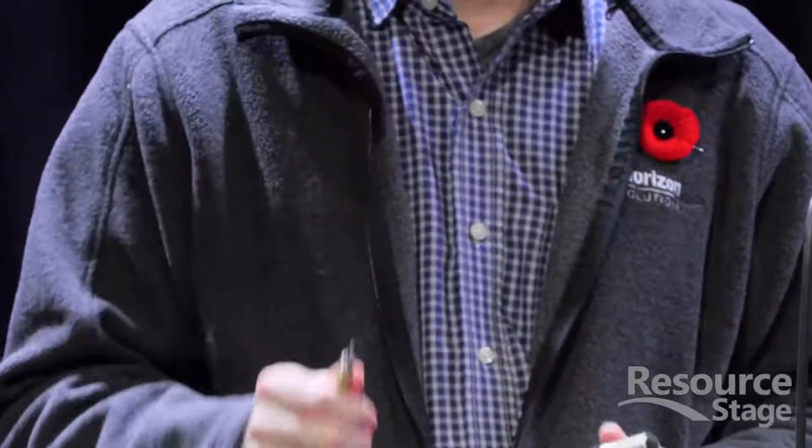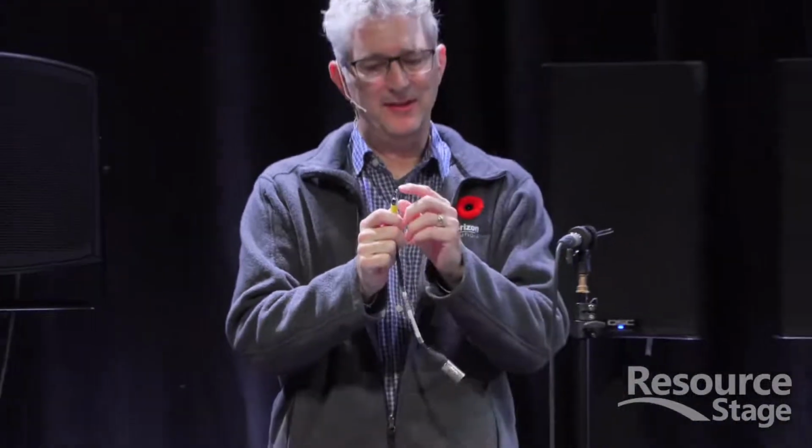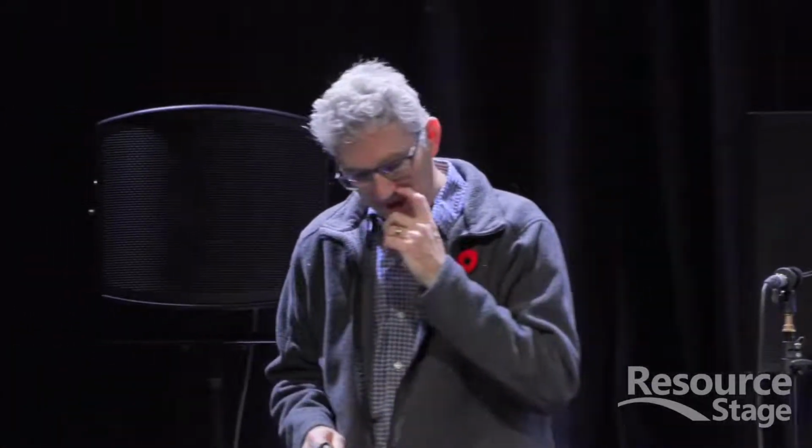But you're going to run into problems, as I was talking about on that other cable, because your phone is sending a left and a right and the ground, and then this is your balanced input, which is going through the differential amplifier, and it's going to sound really, really bad. So that's not going to work to do that. We have this cable for another reason around the shop here, but definitely not that.